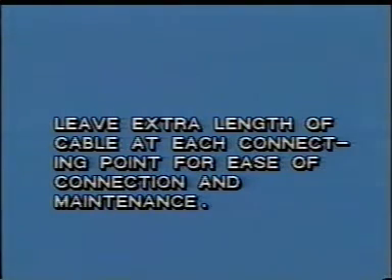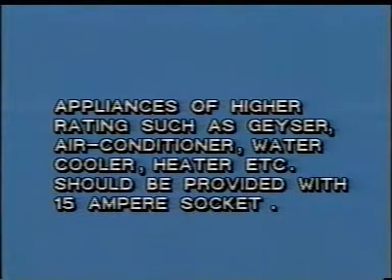Leave extra length of cable at each connecting point for ease of connection and maintenance. Appliances of high rating such as geyser, air conditioner, water cooler, heater, etc. should be provided with 15 ampere socket.